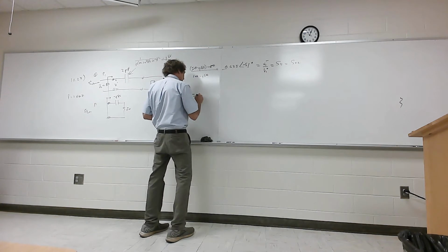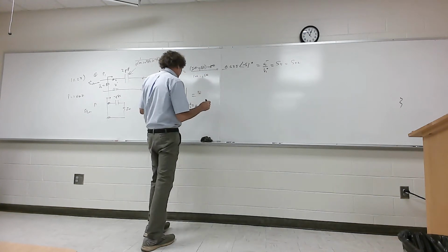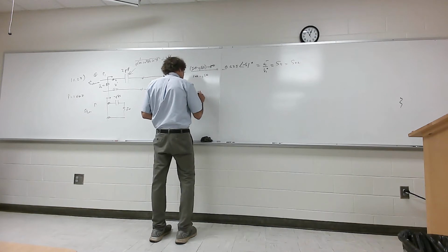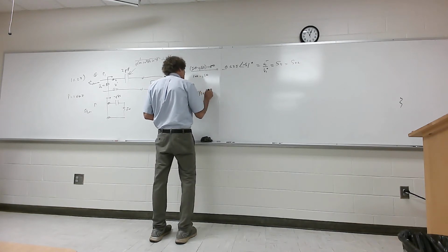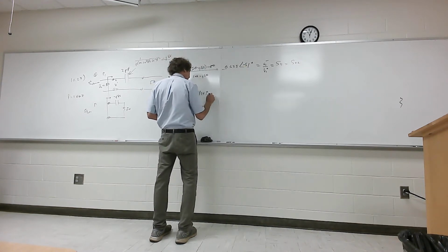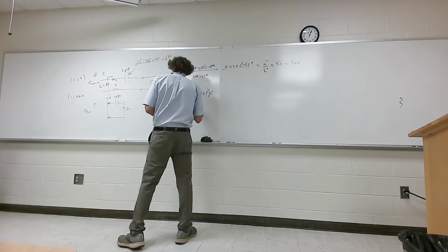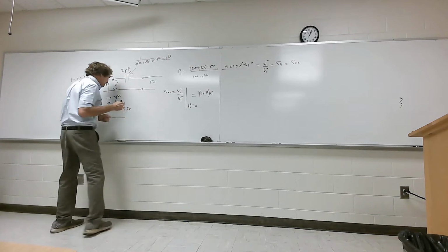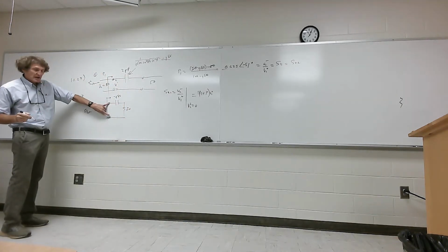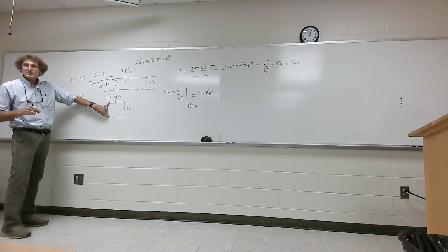So this is going to be, I'll do it this way. It's a transmission coefficient, which is 1 plus the reflection coefficient, times V1 plus, right? And then we have to find the voltage division that occurs. Now that would be the voltage right here. Y'all follow? Understand? That's the voltage just on the other side of the transmission line.